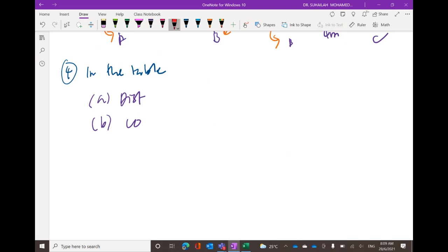For carry over, we need to remember that there are two conditions that we need to consider. We need to consider the far end condition, and for far end pin, the carry over factor is 0, and far end fix, the carry over factor is equal to 0.5.